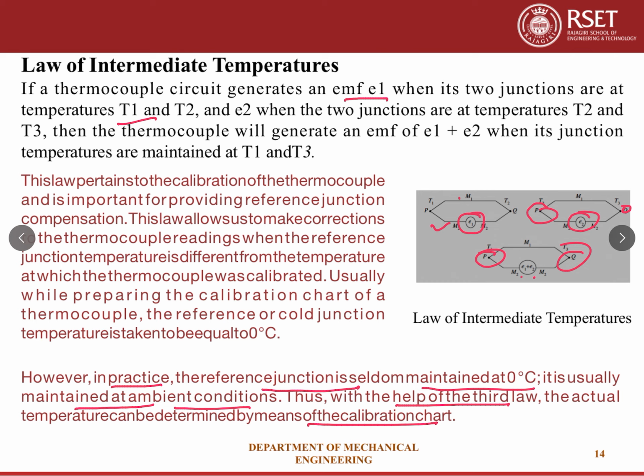So generally, theoretically, we consider the reference temperature to be 0 degrees, but in the actual case, it is usually maintained at ambient condition. Therefore, we can relate the EMF with the help of this law. With the help of the calibration chart, we can calibrate the instrument. So that is the law of intermediate temperature.